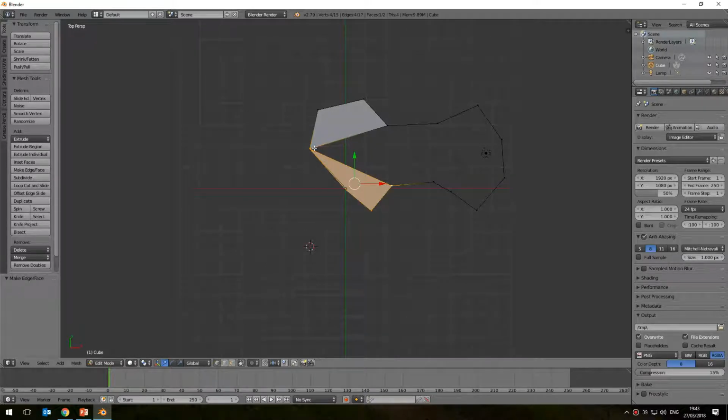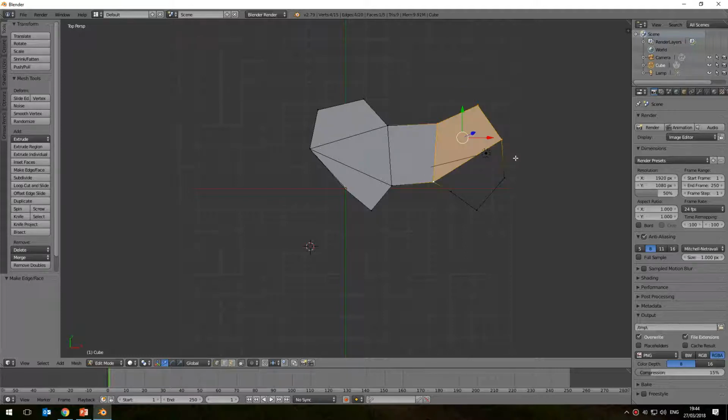Next I'm going to select this dot, and this dot, and fill in that triangle there, like that. And then I'll do this square in the middle, so I'm going to right click on that one, then hold shift down and click on that corner, and that corner. Let go of shift and press the letter F to fill that area. Once again, I'm going to right click, hold down shift, and then select 3 or 4 corners over there and press F to fill that area.